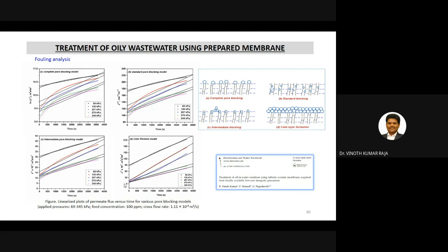These examinations throughout the microfiltration study relate to the life of the membranes. Because the cake filtration facilitates exterior fouling, which may not contribute considerably towards irreversible fouling of the membrane.